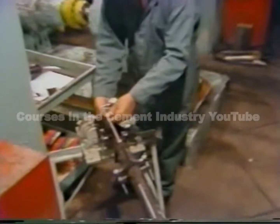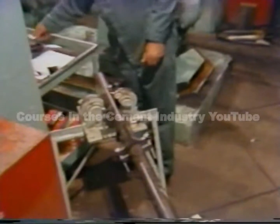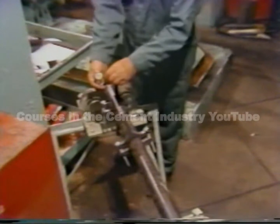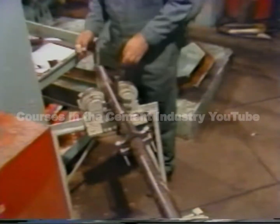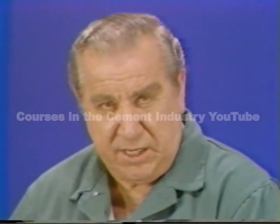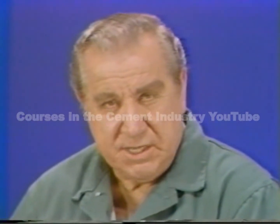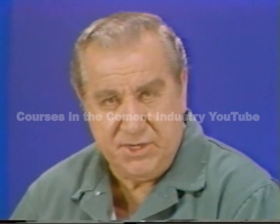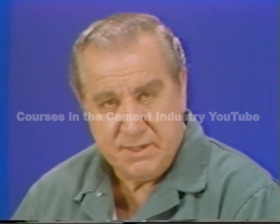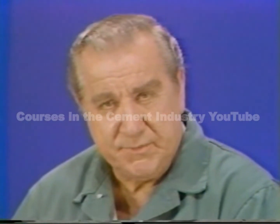Now that he's determined the amount of rod sag, he can remove the dials and prepare to mount them on the shaft. The important thing to remember about sag is that it only affects the bottom parallel or offset readings. That's because the parallel dial is mounted in a way that causes the plunger to come out when the bracket sags. The outward movement is, of course, what accounts for the negative reading on the dial.